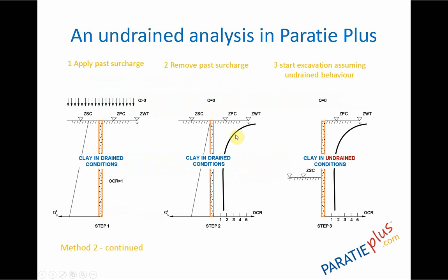Essentially, we propose this procedure. We have to determine in some points an undrained shear strength capacity that we want to match with this history. So, as we will see later, we can calculate some over-consolidating surcharge that we must add at the very beginning stage of analysis, taking care that in that condition all the clay soil must have drained conditions.